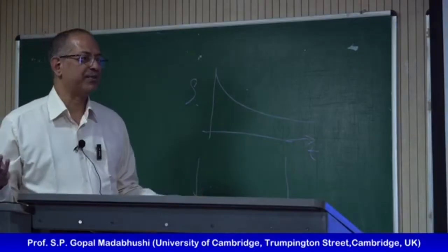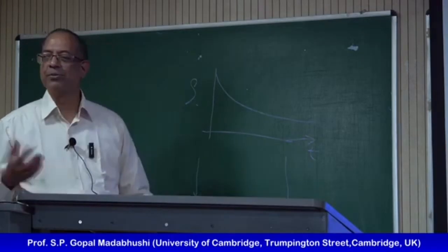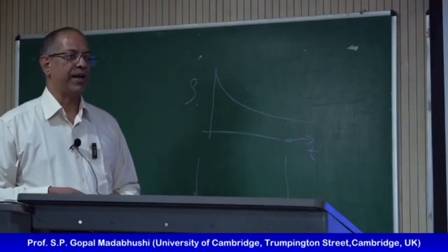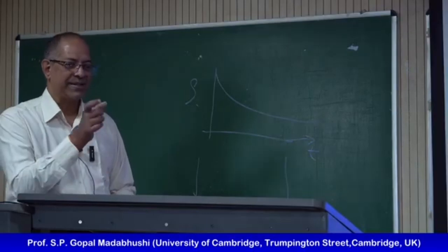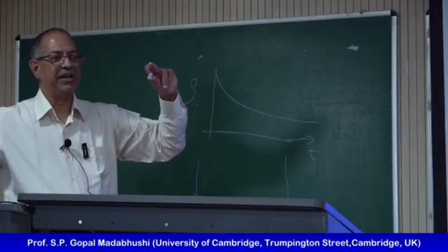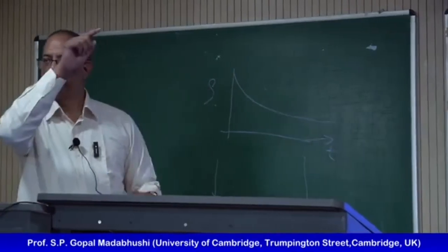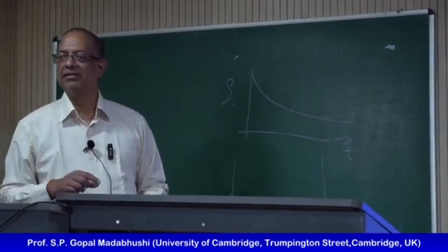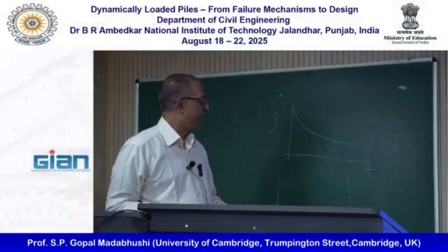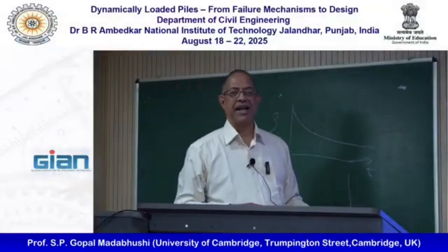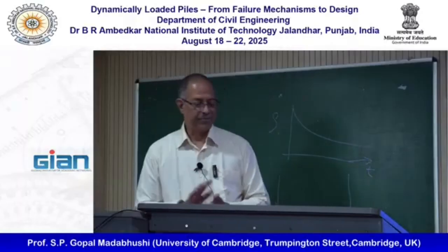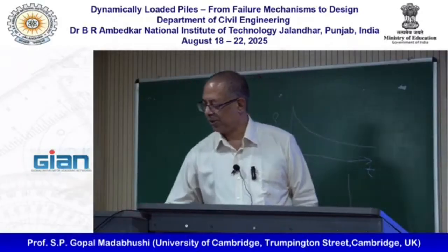It has to change. There is no question, because we know from consolidation we already derived that the x-axis should scale as 1 over n squared. And if that scale factor is different, I know the final pressure I get to and the initial pressure should be the same, but the curve they follow will be different. So the rate of consolidation will be quicker for the 100 G test compared to the 75 G test. Okay. I think that's all I wanted to do.